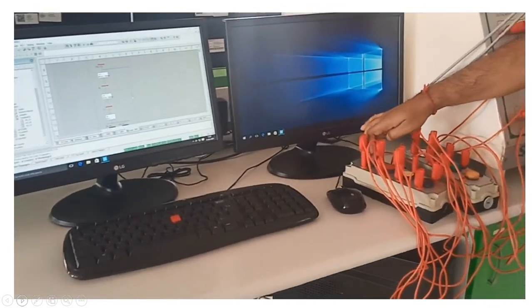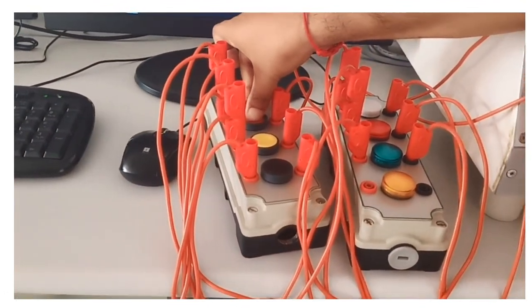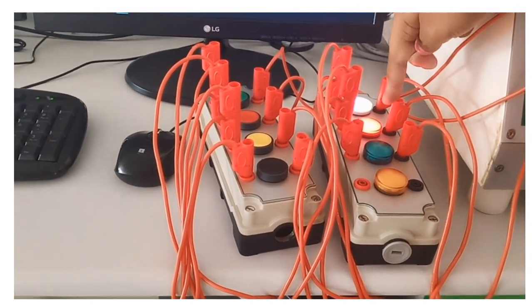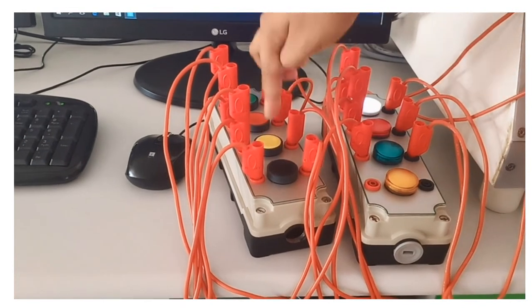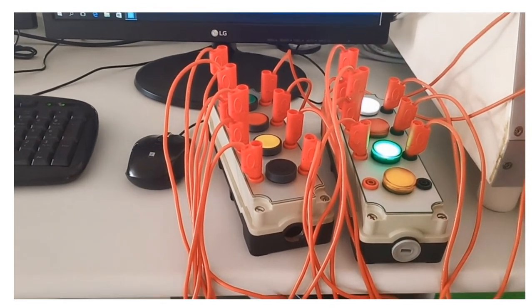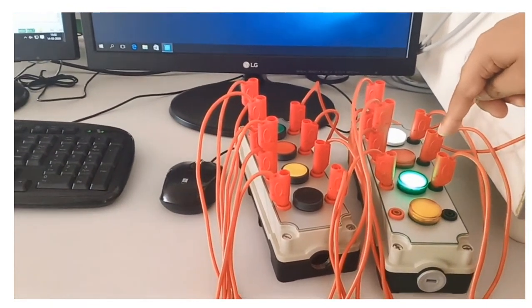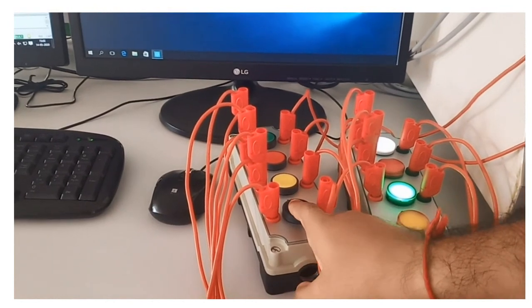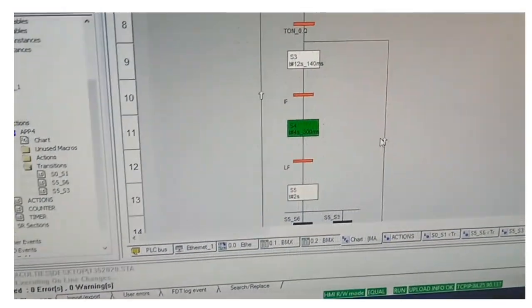So first I have pressed the push button and it is in the high position, then workpiece is there. So the drill motor is on and it has started to extend. Up to the low position it will extend. It reaches the low position and it will drill for some time and it will start to return back. It will return back up to the intermediate position. So here you can see this is the intermediate push button. I'll press it. So the intermediate position it reaches and once again it checks for the cycle.